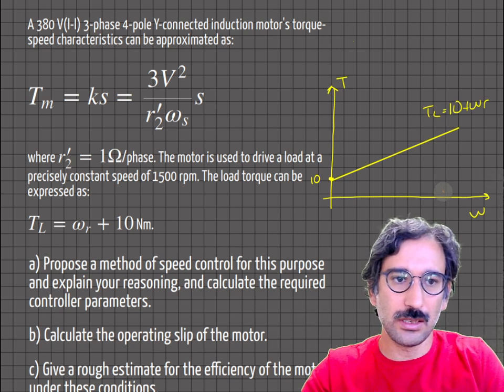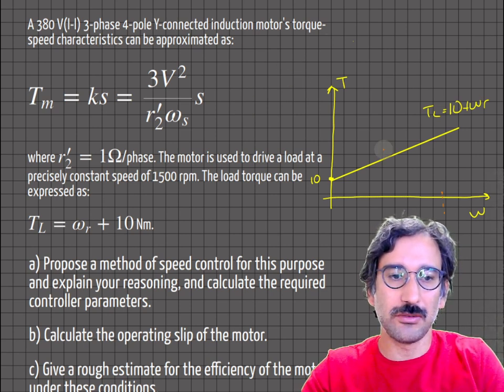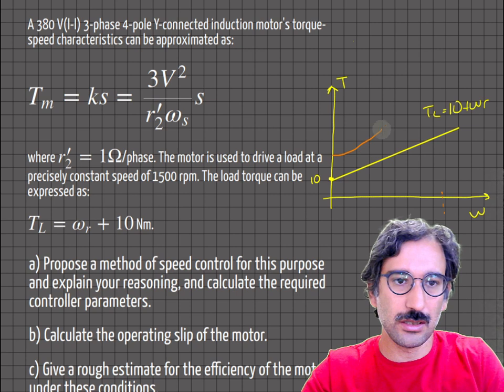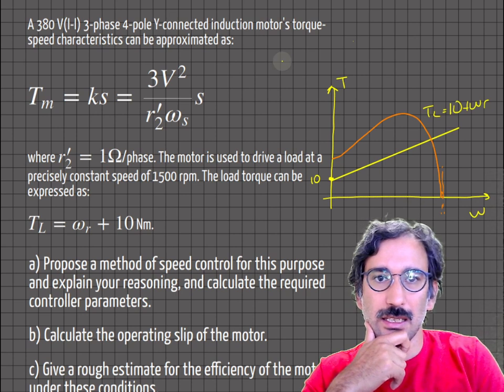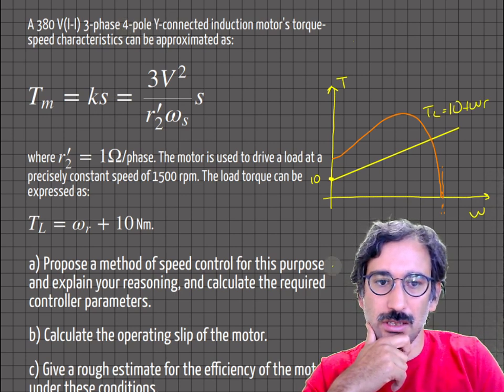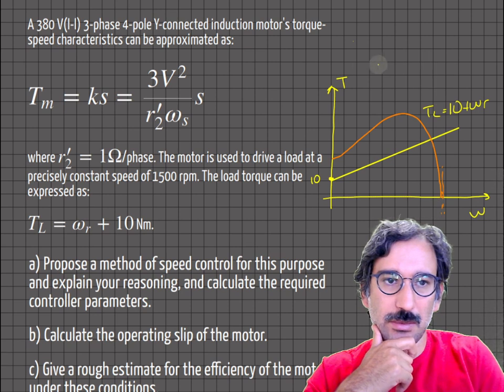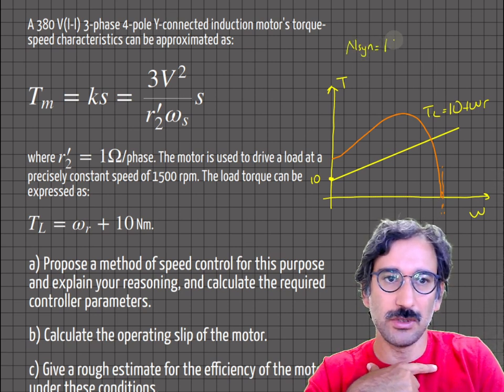So actually if we draw that thing, I think it's not given in the question, but it is driven by 50 hertz waveform. If it is something like that, say this is the synchronous speed, and if this is a 4-pole machine, okay, so the synchronous speed for a 4-pole machine will be 1500 rpm.